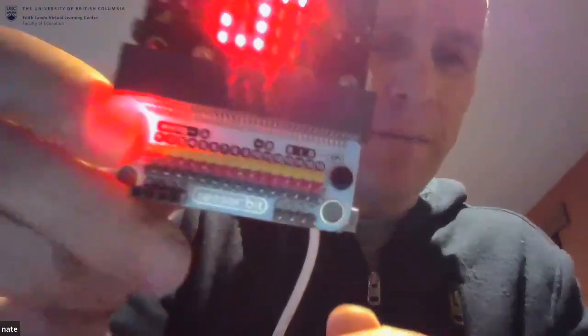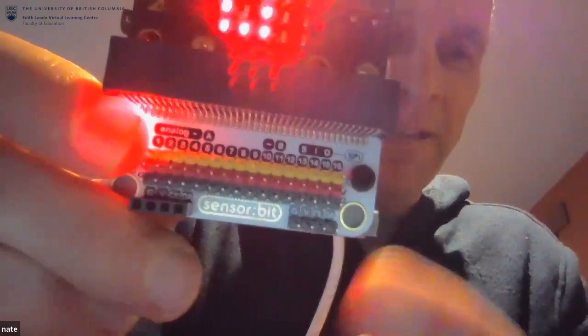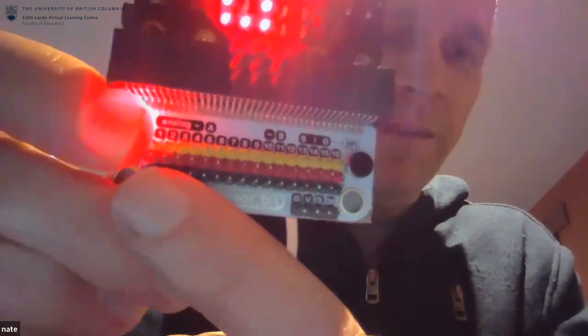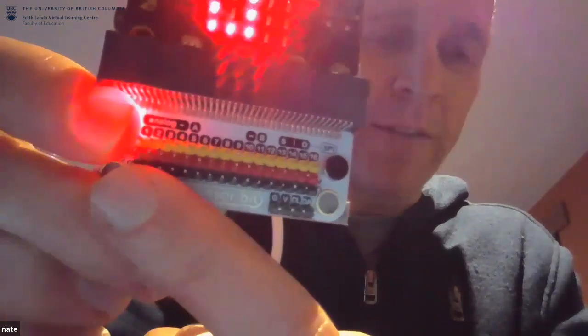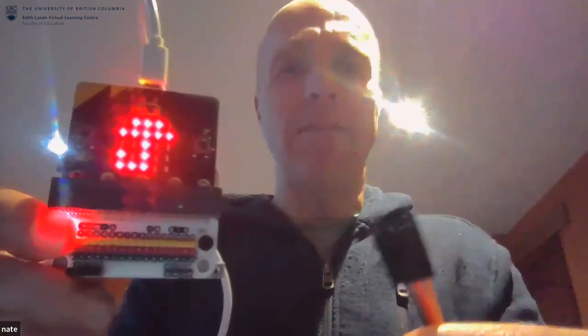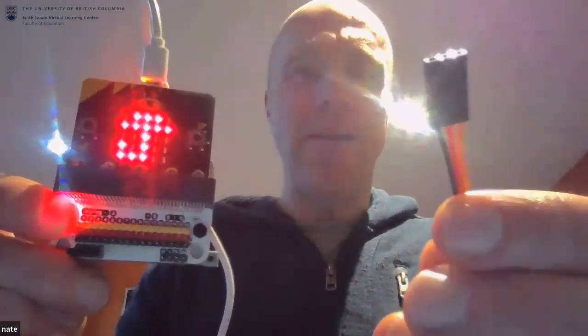There is a pin number 1 on the side. You can see way over here, there's pin number 1 right there. So there's pin number 1 and pin number 2. So you want to grab your servo, and your servo has an orange, a red, and a brown. You want to make sure that the orange is plugged in to the top, the red is in the middle, and the brown is on the bottom.